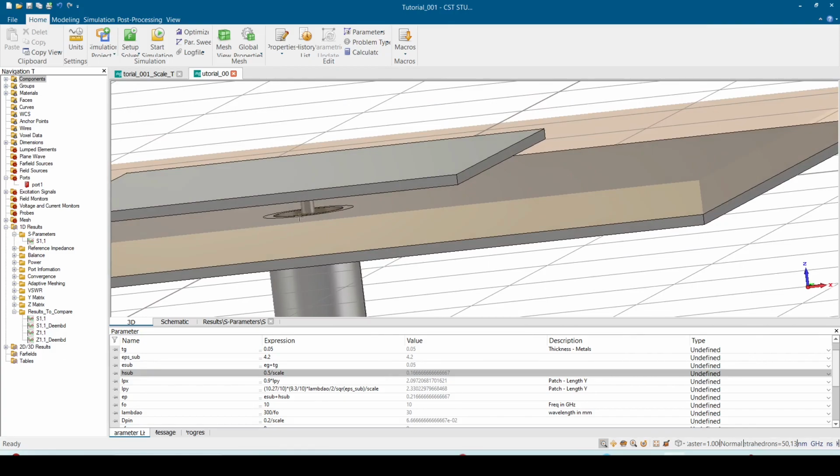So we can have it as a starting point, we scale everything, and then we make sure that we have the proper performance, and then we have to rematch the patch antenna. I will actually introduce a different video for how to do this. But this is just one piece of advice, that you have to revisit this generally if you want to scale.